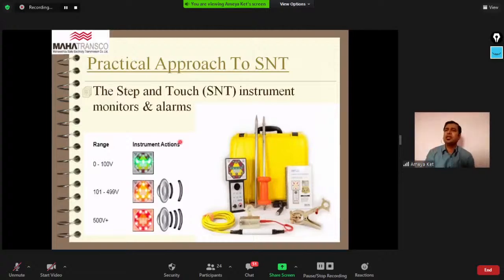One more question may strike your mind: in the substation we are not checking the earthing, but, my dear friends, throughout the year we are maintaining the earthing. But in transmission, it is very difficult and cumbersome to maintain the earthing, as we do very frequently in the substation. So something is expected for cross-verification of a particular tower's earthing in an emergency, to highlight whether the tower is safe or unsafe, even in the dead line case, for climbing.